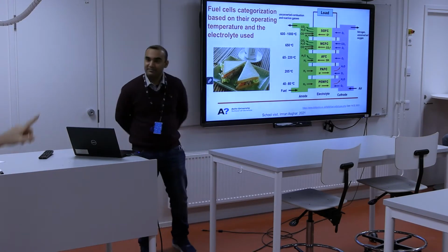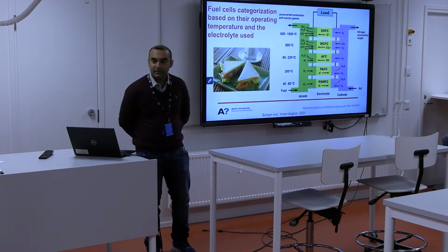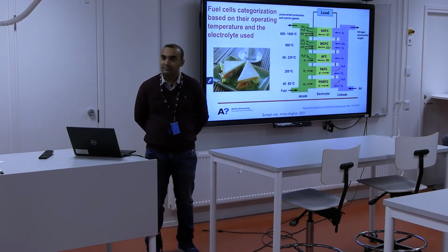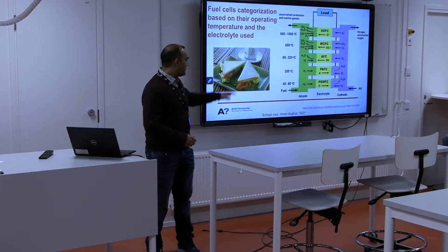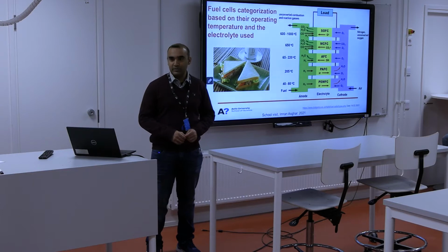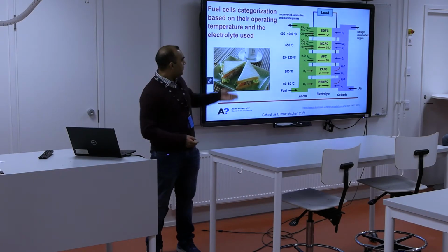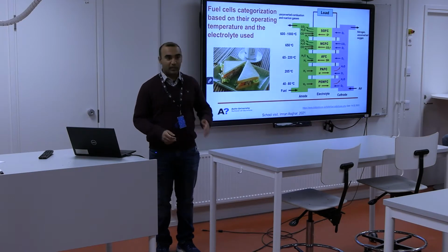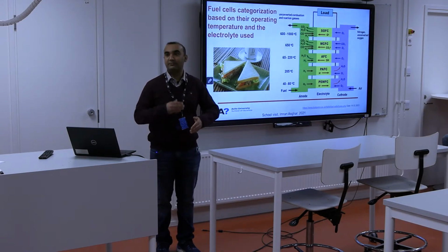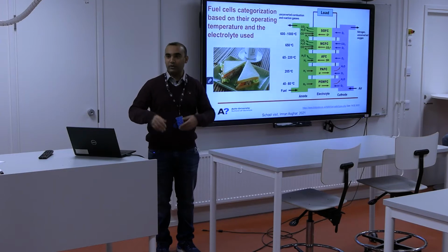What electrolyte would you choose if you want to build an automobile? Automobile, yeah, I think for most of these automobile applications, the lower temperatures are used, because one of the disadvantages of the higher temperature ones is long startup time. If you have a vehicle and you are using a very high temperature fuel cell, it will take time to heat up before it starts operating.